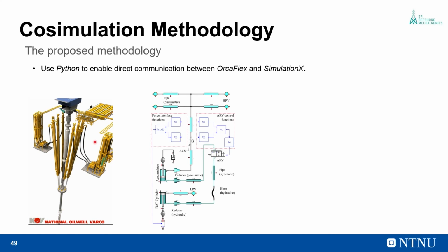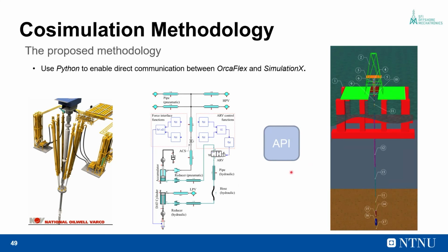So we develop the Simulation X model for the riser tension system, where all the components are modeled, including the pressure vessels, the DAT cylinders, the accumulator, and the anti-recoil valve. And we use the API interface to connect it to the Orcaflex model, where we model the semi-submersible drilling rig, the wellhead, and the riser connecting the rig to the wellhead.